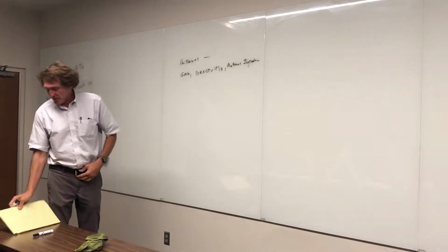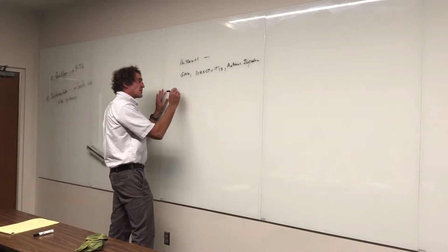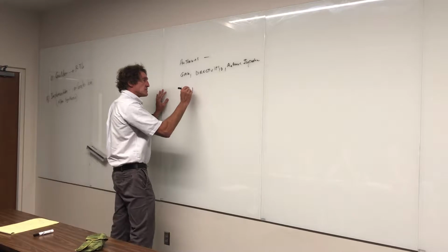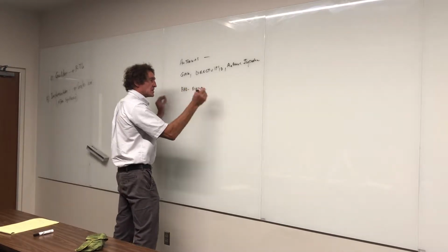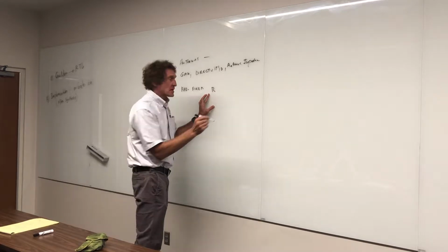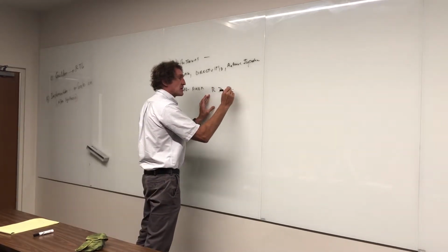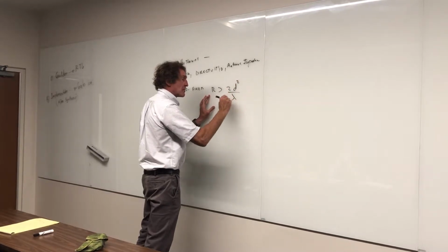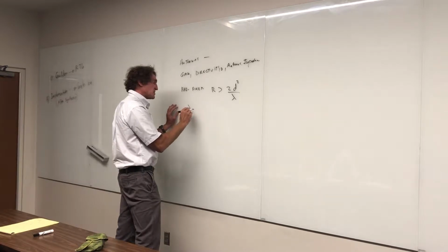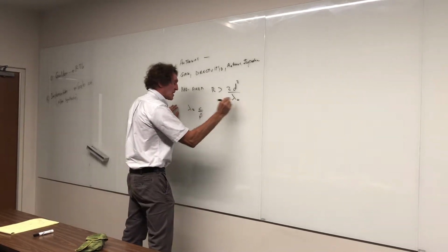This is an equation. Well, I'm going to just show this to you. This is the most common form of this. It says you have to be, for the far field propagation, a distance r from the antenna in any direction. And it has to be greater than 2 times something, it's really D squared over lambda. Now lambda is just free space lambda, it's c over f. You can call it lambda naught.